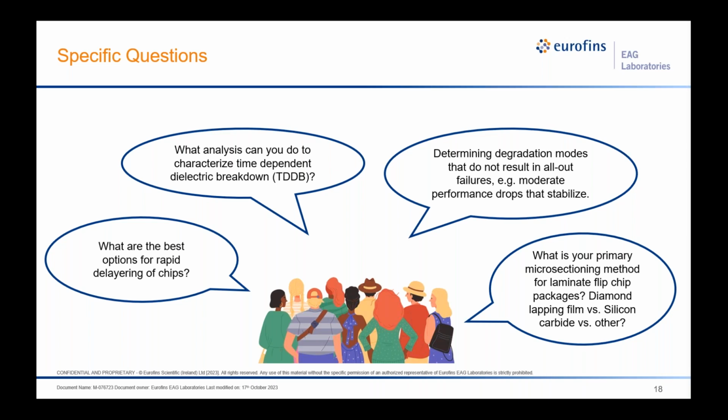And so the goal here is, there are different types of TDDB testing. One is where you aggressively step up the voltage until failure. And the other is where you have long settling times and you let it stay biased at certain voltages, and you slowly step it up. So one is more the time-dependent breakdown and one is more the voltage-dependent breakdown. After it actually does break down, we'll do physical analysis and understand why it failed and where it failed. That'll give them some confidence that their fab process met their acceptance data. It's generally mostly requested by the fabs, but we can do it in other scenarios, so we can talk about that case by case.